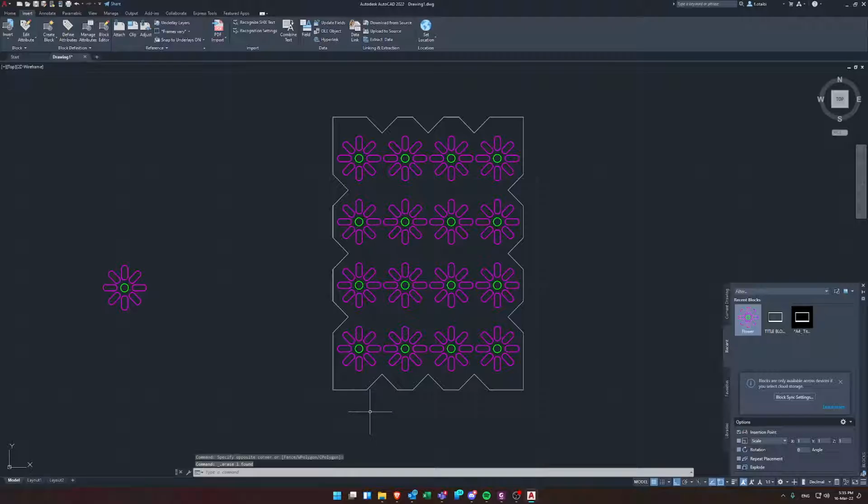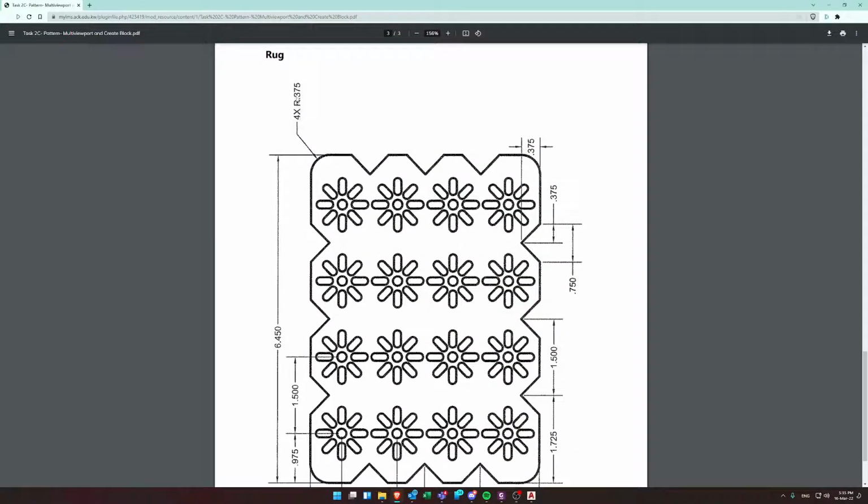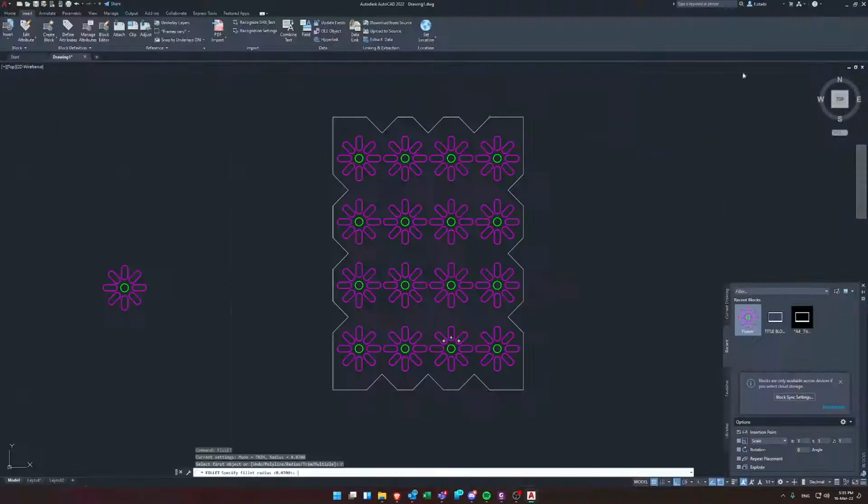So we say, okay, what's left? Well, we rounded these corners, right? So what command would we use to round corners? Well, it's fillet. So fillet, and we press enter for that. Again, we want to use the radius, so R. What radius are we going to use? Let's check. You can see it at the top, 0.375. So 0.375. 1, 2. Again, choose multiple. 1, 2.